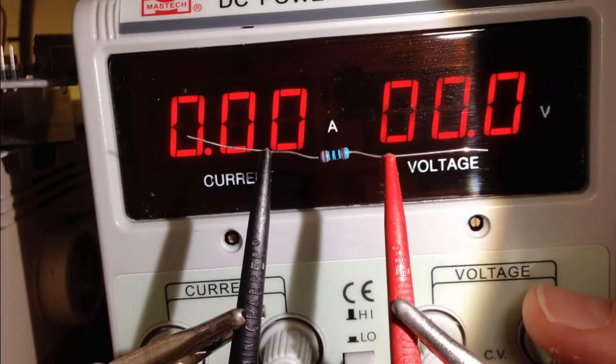I did an experiment for you to illustrate the concept of properly dimensioning an electronic component for the power that we expect it to dissipate. So what we have here is a quarter watt, 0.25 watt resistor with 220 ohms. Let's see what happens as I ramp up the voltage. So this is a lab power supply. On this display you see the voltage, and over here you see the current. So let's see what happens.